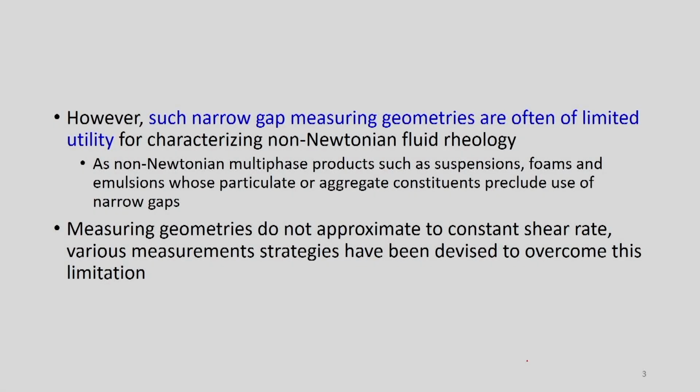However, such narrow gap measuring geometries are often of limited utility, especially for non-Newtonian fluids, because non-Newtonian fluids are generally multiphase products such as suspensions, foams and emulsions. So, if the gap is very narrow, the particles, droplets or bubbles in the non-Newtonian suspension may break up, and obviously the property of the material may change under such narrow gaps,